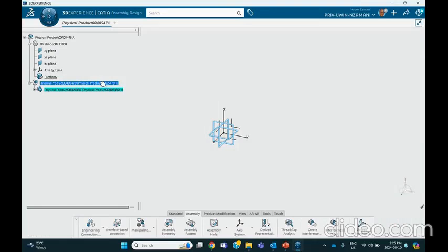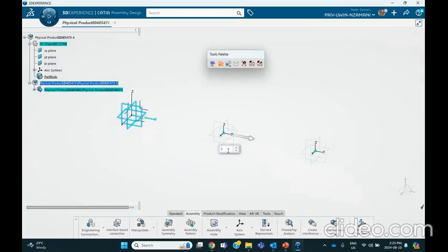As explained in tutorial 18, while you're here, you put the cursor on this and you click on it and say linear multi-instantiation. And right now it's doing it in the direction Z. I don't want it. I want it to be in direction Y. And I want 8 of them. So I change this to 8.